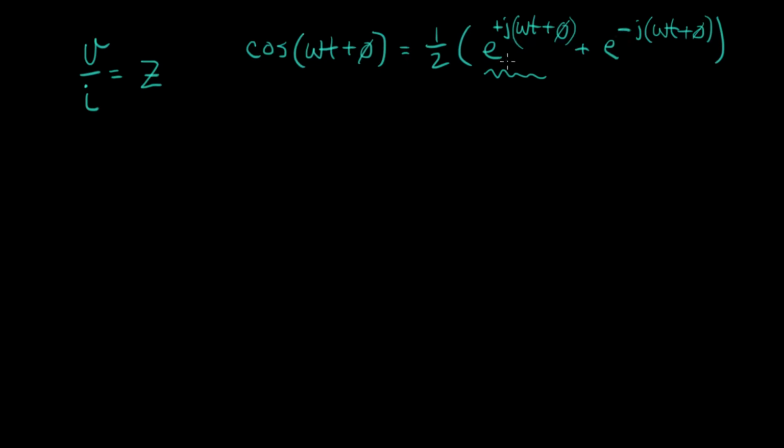And so when we made up the concept of impedance, we assumed that V or I was of this form, this complex exponential. And when we put that through our components, we came up with the idea of impedance. And as a review, the impedance of a resistor turned out to be just R. That's the ratio of V to I in a resistor.